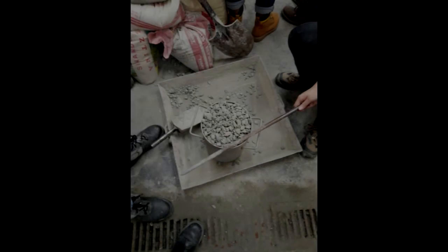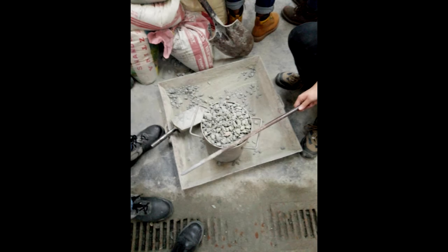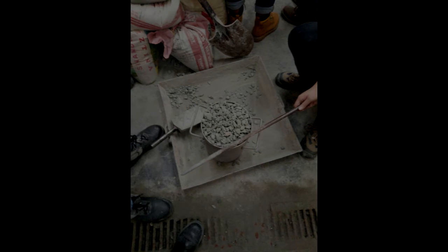Similarly, the jigging method was done. It was done by filling the container 1/3 full, then jiggling it 50 times. Again, this was repeated 2 more times until it was full. The shoveling method was done by filling the container and patting it down using a shovel. Afterwards, all the outputs of each trial were weighed.